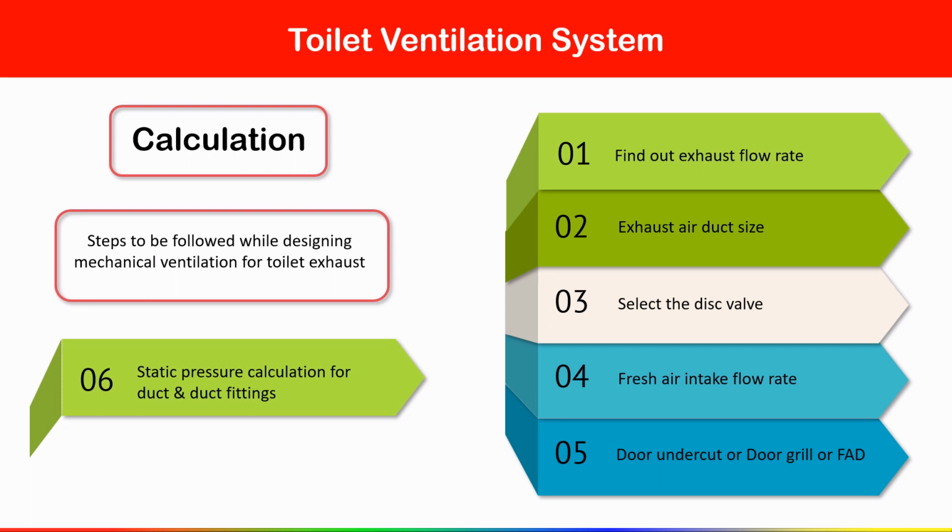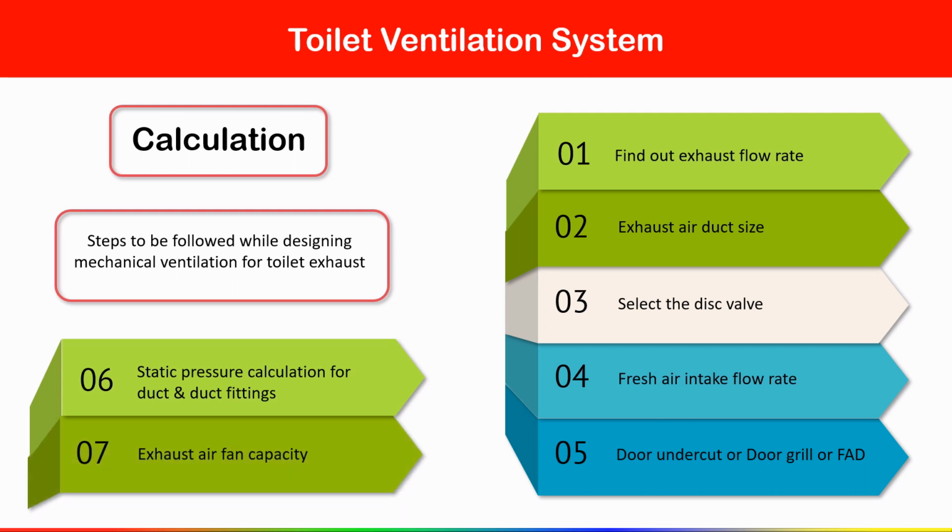Now the sixth point is written: static pressure calculation for duct and duct fittings. So again, suppose you are given the duct work for extracting bad odor from the toilet. How can you get the capacity of the fan, the inline fan which you have installed inside the duct? To find out that capacity of the fan, first of all we have to calculate the static pressure. Based on that pressure only you will get the capacity of the fan.